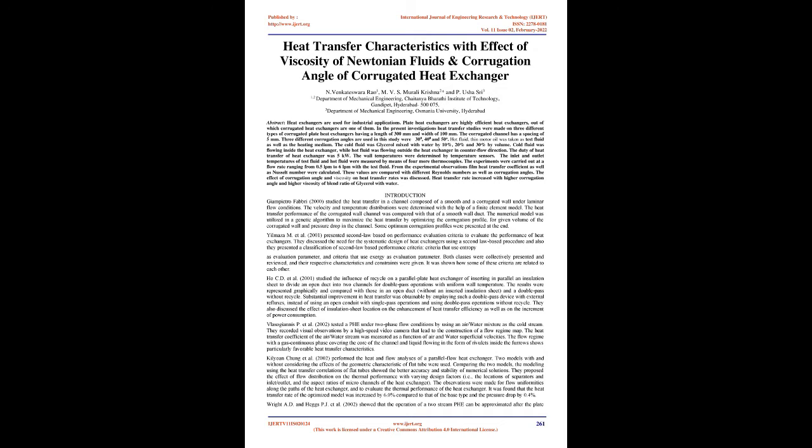These values are compared with different Reynolds numbers as well as corrugation angles. The effect of corrugation angle and viscosity on heat transfer rates was discussed. Heat transfer rate increased with higher corrugation angle and higher viscosity of blend ratio of glycerol with water.